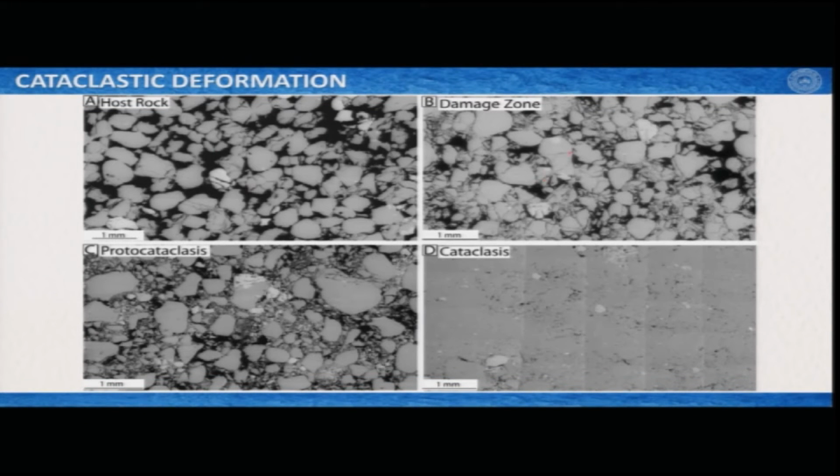So, you can see that these grains are getting fractured here, here, here heavily, like they are getting crushed, like someone hammered it. Okay. And then these grains do rotate by themselves, but they cannot. So, they produce further fractures and they get some sort of sorting. So, you have large grains here and here, which are filled by fine grained matrix.